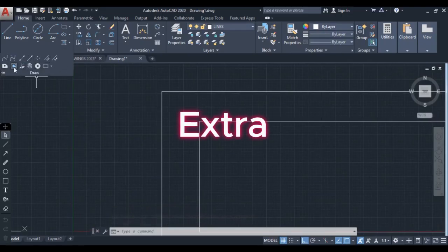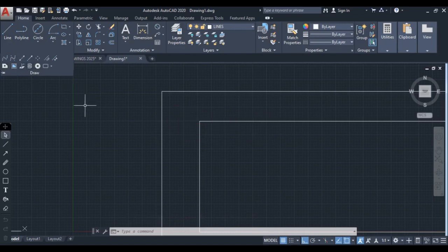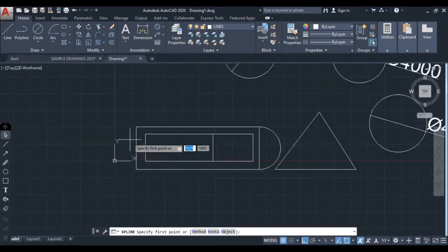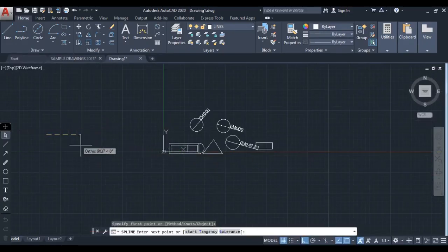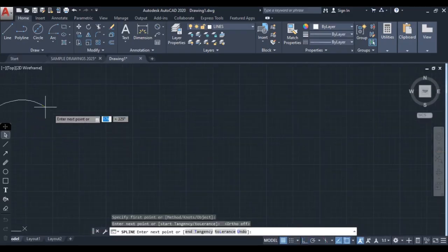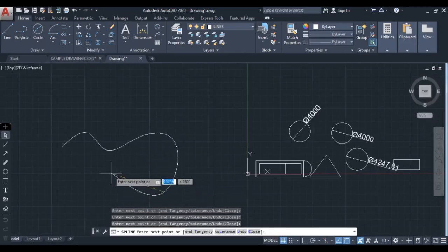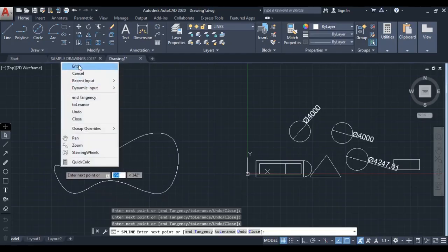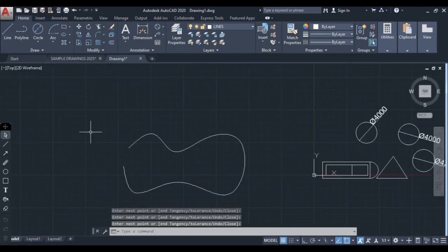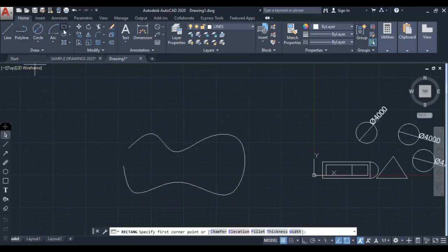Now let's move over to this other portion. I promised to teach you how to use some of these tools here, and I'll start with the first one. Spline fit. This line is used to draw simply curved lines. You just click on it. Make sure your auto mode is not on. You click up. You can see you can draw curved lines with it, and you just hit enter. That's it. So you can use it for any creative work you want to do.